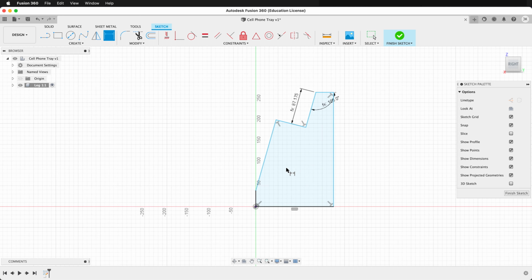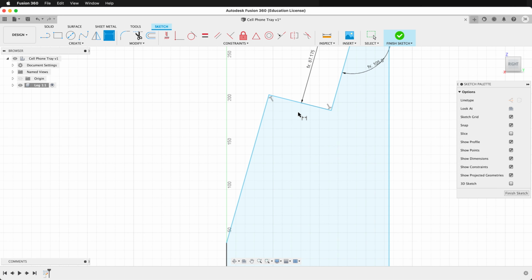So then we can continue defining our sketch. So for this dimension, I'm going to bring this down at an angle here. And for this one, I'm going to go ahead and I'm going to say device thickness plus ply times 3. So now that's much skinnier there. And again, my sketch has moved around, so that's fine. I can just bring this up.